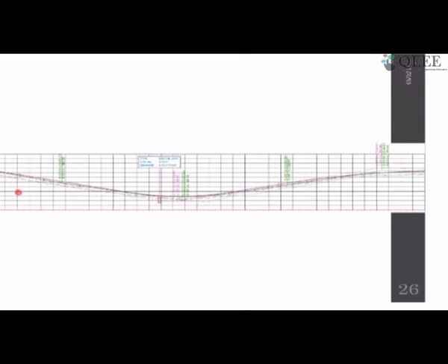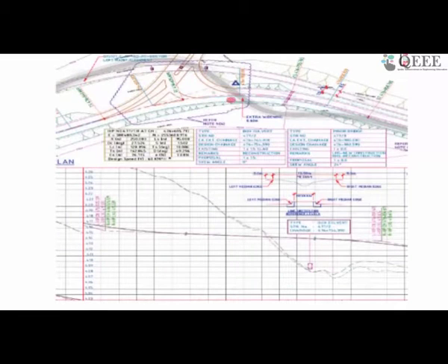So here, as I told you, in the valley curve, we have to be careful whether there is any cross drainage structure, because this is the critical point. Water is going to come down from this side, and on this side we need to make sure they have adequate drainage. And here you can see the cross drainage structure. So when someone is reviewing or designing, they need to make sure that there is a cross drainage structure and there is sufficient provision for water to flow out. And this is the complete criteria of that.